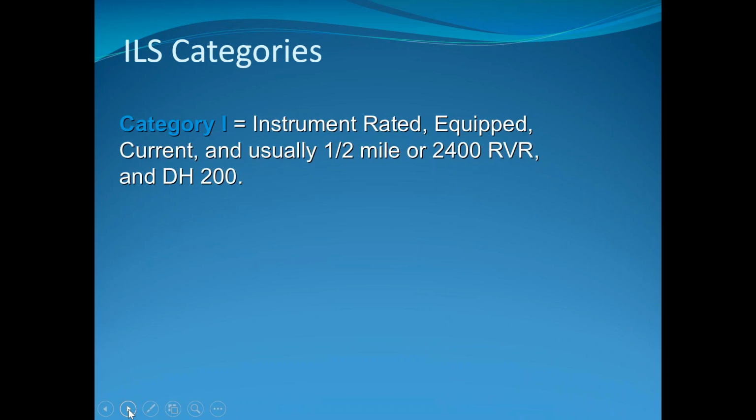So when we look at this criteria that it's giving here, these are weather minimums that it's telling us. A half mile is the Category 1 limit. That's as low as you can go down to visibility-wise and still land. So if it's below a half mile, then you basically can't land the plane. You can't shoot the approach essentially, or even fly down it.